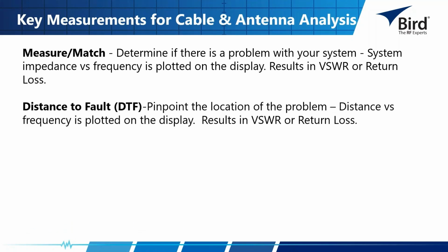We have distance to fault, or DTF. This pinpoints the location of the problem. Distance versus frequency is plotted on the display. And you also get your results in VSWR or return loss.